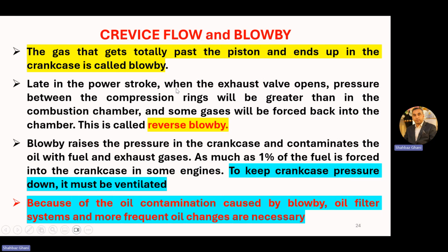Some gases will be forced back into the chamber, because there is a passage available: the gap between the piston walls and the cylinder walls, and the piston butt gap. So some of the gases will be forced back into the chamber. This is called reverse blow-by.